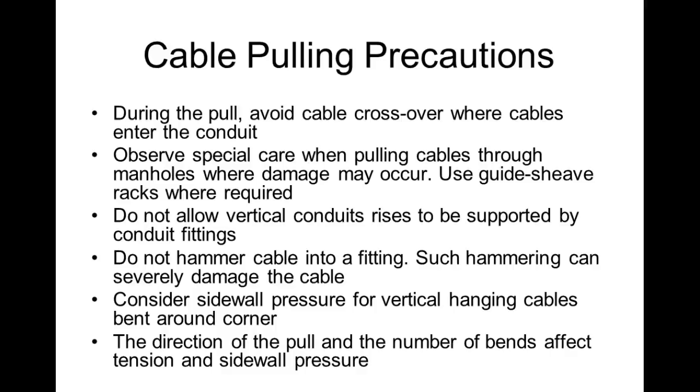Consider sidewall pressure for vertical hanging cables bending around corners. We have people that'll take cables up a long distance and then others lay them over a corner of something. And what's the problem? Well, that corner is supporting all the cable weight, right? You understand that? People don't understand. It's like roofs. If you've got shingle roofing on your house, you pick up one of those shingles, they don't weigh hardly anything, right?